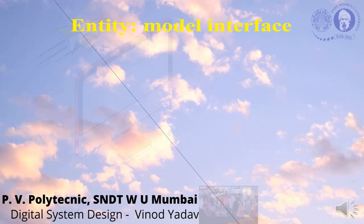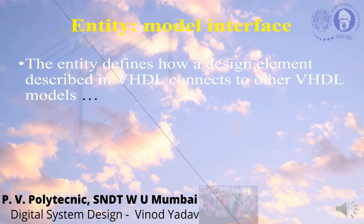So as we know, in all the three we have used entity. Entity is a very important thing, and it is a model that interfaces architectures. This is a model which defines interfaces. The entity defines how a design element described in VHDL connects to other VHDL models. There we are defining the input and output of the architecture, whichever we are going to use.